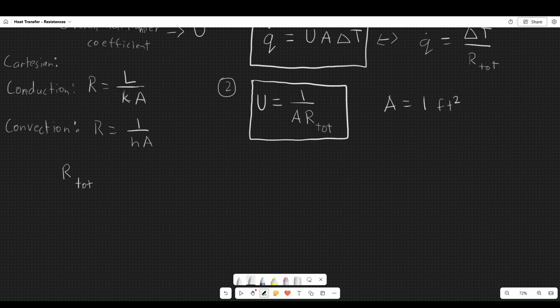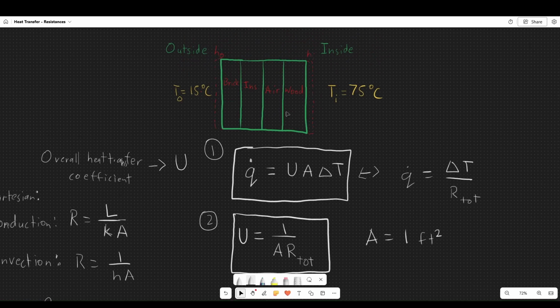All right, perfect. So now that we have this, the second thing that we have to do is figure out, well, are all these materials in series or parallel? Kind of think of it as a circuit, if you have to, where we can have these materials in parallel, in which case, in order to get the total resistance, you inverse sum these, or we could have them in series, right? We could go like this and then go like this.